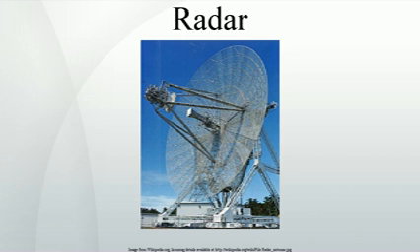More sophisticated methods of signal processing are also used in order to recover useful radar signals. The weak absorption of radio waves by the medium through which it passes is what enables radar sets to detect objects at relatively long ranges, ranges at which other electromagnetic wavelengths, such as visible light, infrared light, and ultraviolet light, are too strongly attenuated. Such weather phenomena as fog, clouds, rain, falling snow, and sleet that block visible light are usually transparent to radio waves.